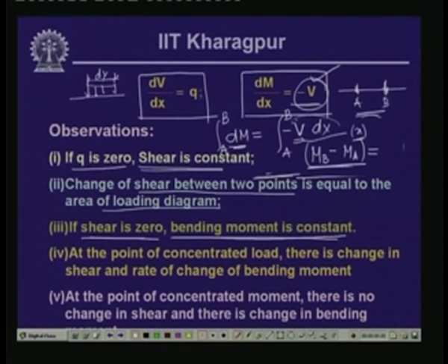So, when we try to plot the variation of the shear force, we can have a diagram of shear force, and integral V dx precisely indicates the area of that shear force diagram, and that in fact we will be looking into as we go along for the shear force and bending moment diagrams.